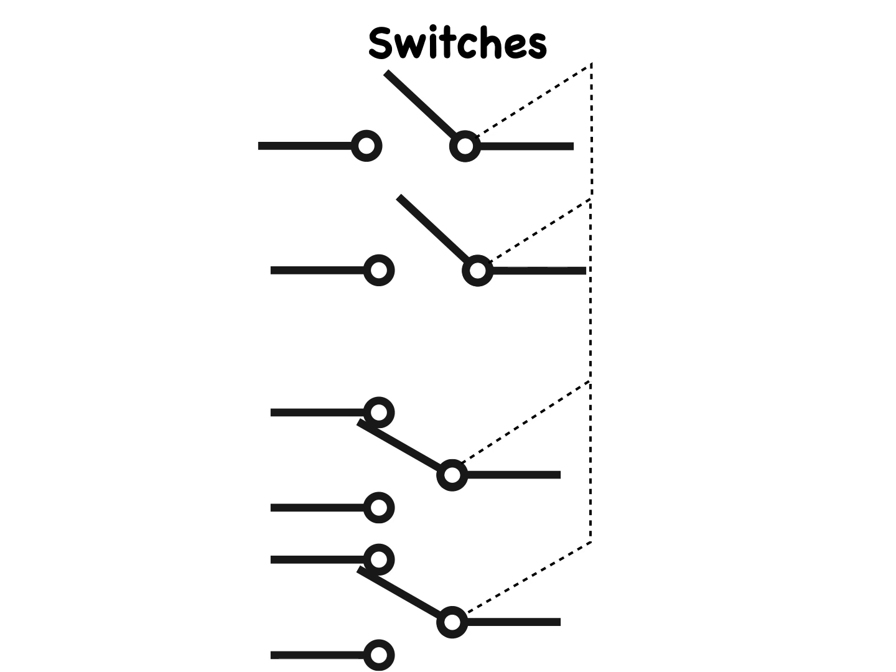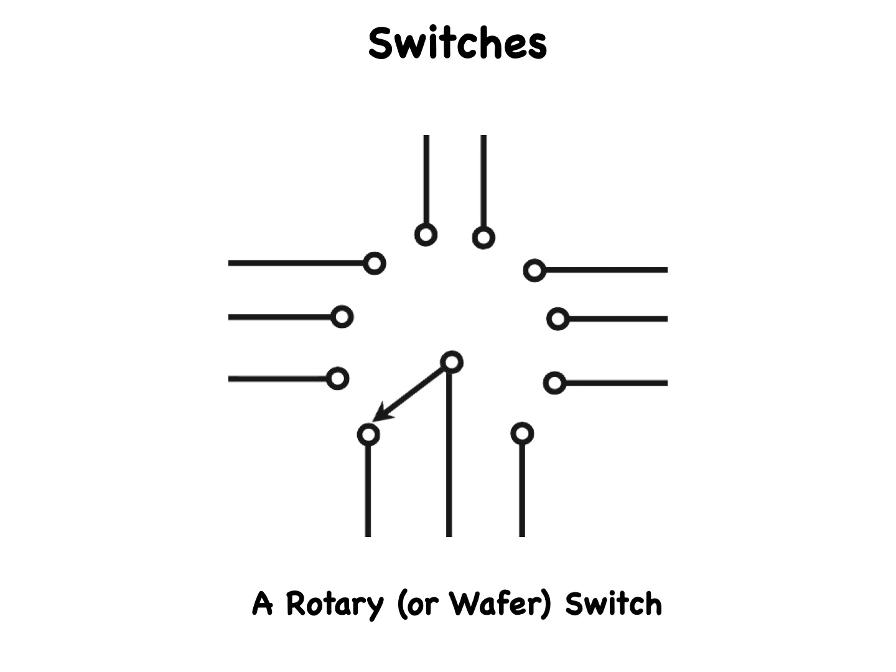This last designation can actually be covered under the heading of multi-contact switches. This category takes in most switches that have more than 2 poles or 2 throw positions. For example, a rotary switch has a single pole and several throw positions. The arrow still indicates the pole contact. In this case, the switch has 10 throw positions. Technically, then, it's a single pole, 10 throw, SP10T, device.